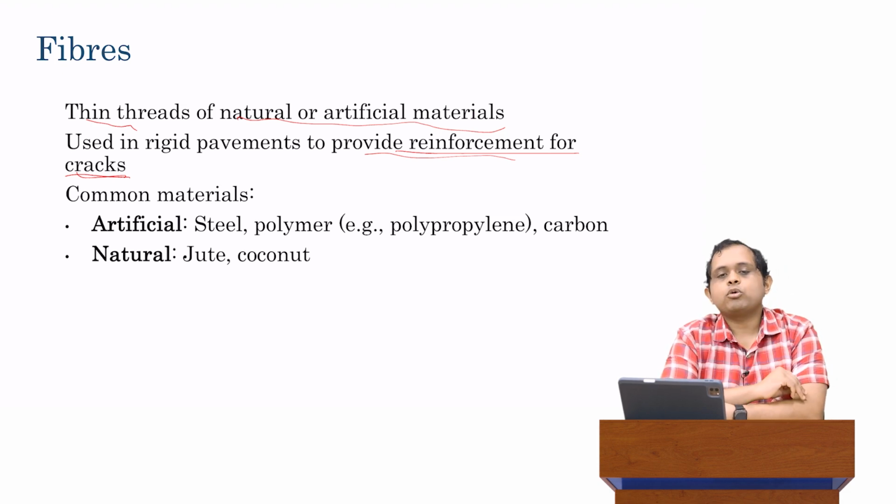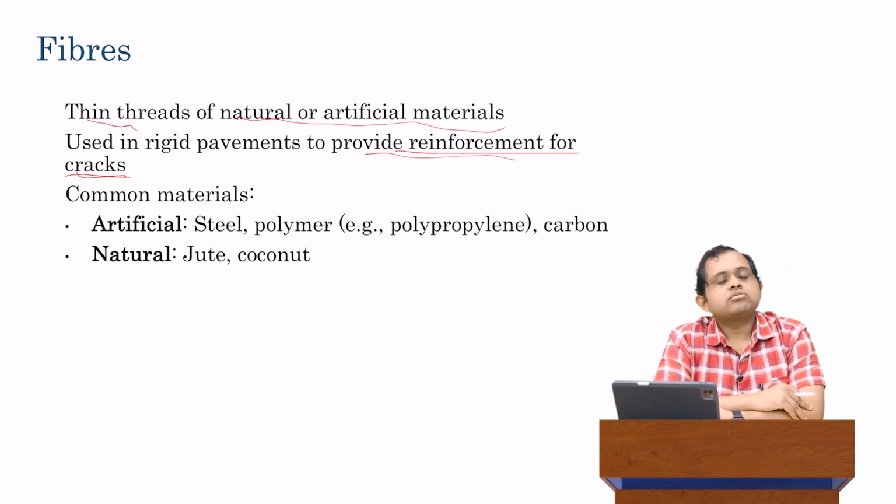That's something very, very important to understand. Whether it's fibers, or steel reinforcement in JPCP and CRCP, steel does not prevent cracking, and fibers do not prevent cracking. Instead, they prevent the crack from opening up too much after the crack has been formed. That's why we call it reinforcement for cracks.